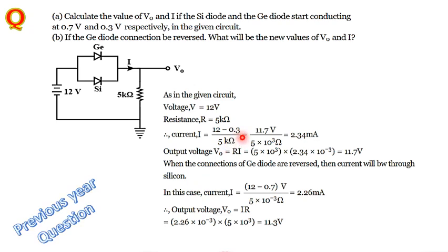In this case, why have they mentioned only 0.3 volt? That is about germanium, not silicon. See, this one has a little more barrier potential, this has less barrier potential. Even while driving, we always prefer the easiest route, right? This 0.7 barrier tries to prevent the further movement of electrons and holes, but here it is only 0.3. When comparing these two, this is a little easier to cross. So this is 0.3 volt and this is 0.7 volt.